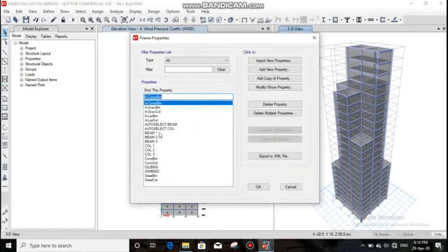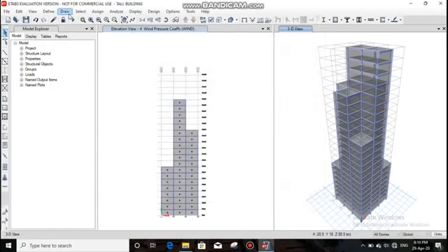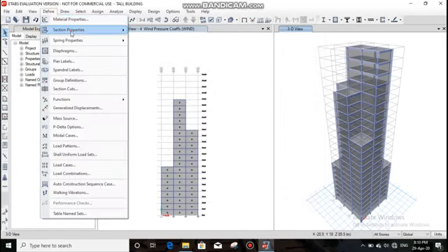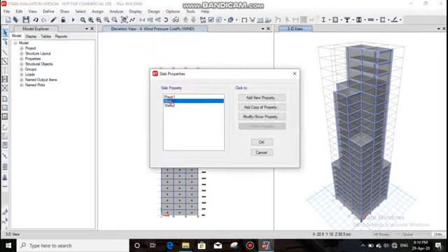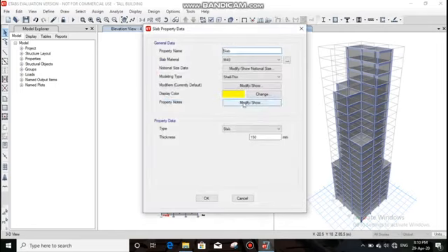Here, as per the given beam and column dimensions, I have set the dimensions of the beam and column. Then I added the auto select beam and auto select column options. Then there is a slab section for the slab dimension. You can see here the details of the slab: 150 mm dimension of the slab, M40 grade.